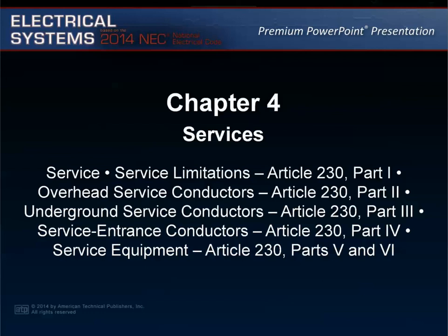Chapter 4 covers services. The service is the electrical supply in the form of conductors and equipment that provides electrical power to the building or structure. The service conductors for the building or structure are either overhead drop or underground lateral conductors. The local utility company brings electricity to the service point. All electrical connections, equipment, conductors, etc. beyond that point are controlled by the NEC.